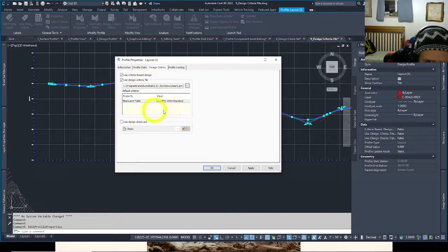This is going to a standard AASHTO. We talked about AASHTO before. We're looking for minimal K values. Remember, that's the sharpness, the ratio, the drasticness of the curve. A smaller K value is a tighter little curve. That's almost like two lines hitting. A bigger K value is a more gradual curve. And we're going to pick in here.